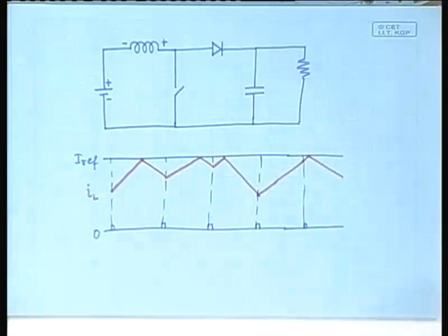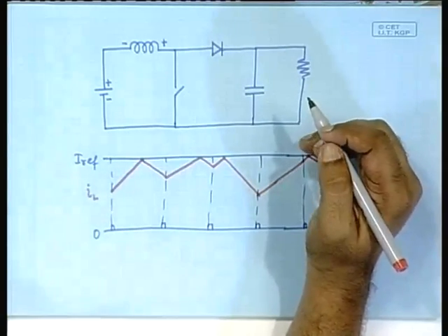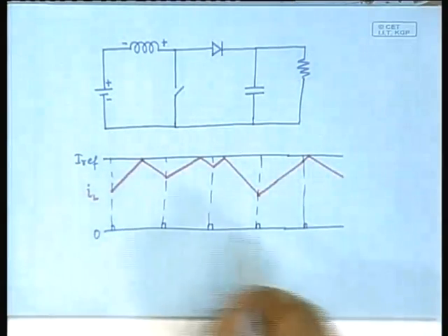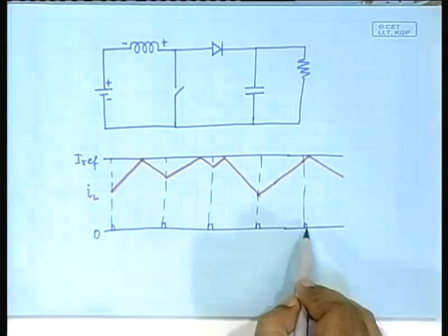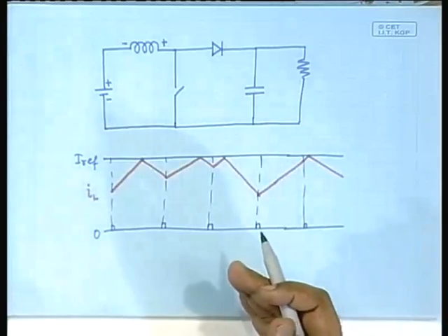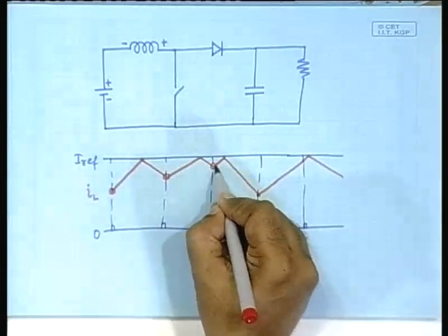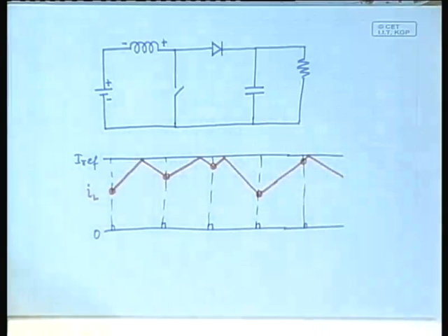Now, suppose I want to obtain the discrete time description of such a system. How will you do it? Obviously, in order to do that, we will have to sample it, because this is a non-autonomous system. There is some kind of external clock, and we have learned that whenever there is an external periodic input, it is a non-autonomous system, and then the discretization has to be done by placing a Poincare section in synchronism with the external periodic input. So, that is what we do. We observe from this point to this point to this point and so on and so forth.